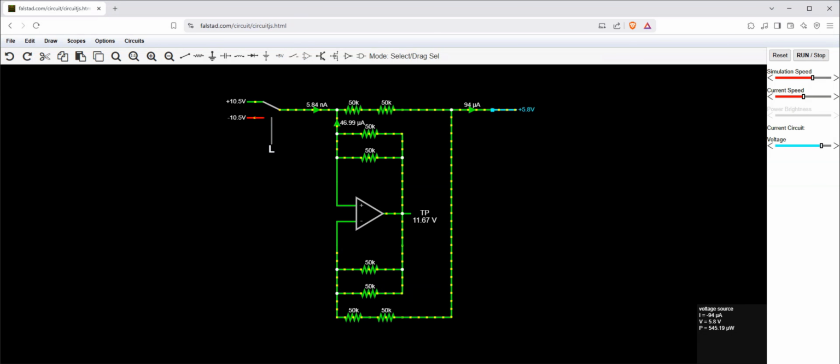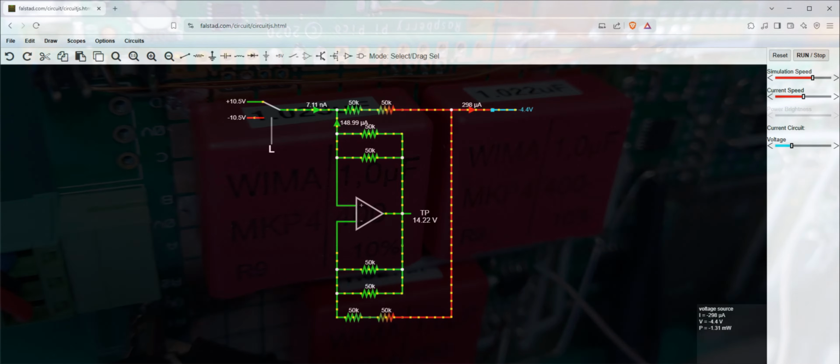I wanted to implement an on-resistance compensation circuit similar to the previous version, but using the 50 kilo ohm resistor network that also formed the integrator R would saturate the compensation amplifier. Since this was not crucial to the operation of the DAC, I decided to not populate the circuit during testing.